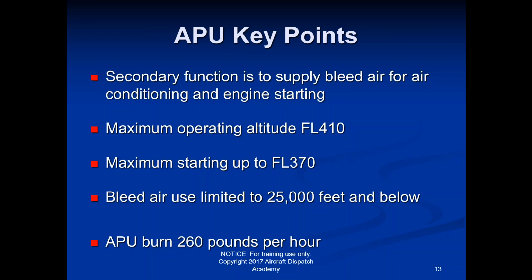You remember how the other day we were talking about redundancy in aircraft? It always has 2 or 3 or sometimes even more systems of each of the same thing, in order to rely on each other. So an aircraft always needs 2 of every system. When an aircraft is functioning under normal conditions, it has 2 electrical generators, one from each engine. As long as both engines are running, or rather, as long as the generator portion of each engine is running, then the APU doesn't need to be on at all during flight.